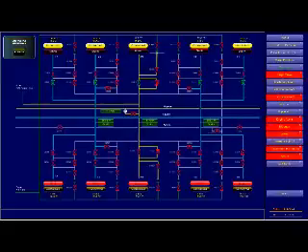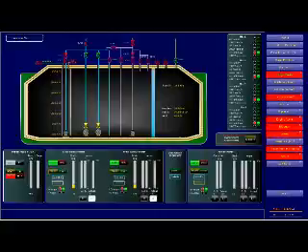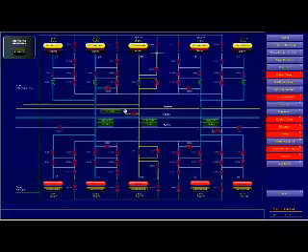What is your tank pressure at the moment? Tank pressure 19.7. Yeah, so manifold pressure 12.7 is okay. So your pressure can be released. Now I will show you what will happen, how to start the cargo pumps. Let's go and we'll try number 4 pump because the ship is trimmed already by the stern. So we'll start number 4 pump.